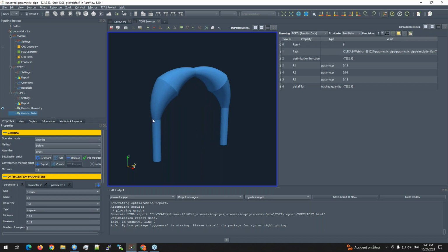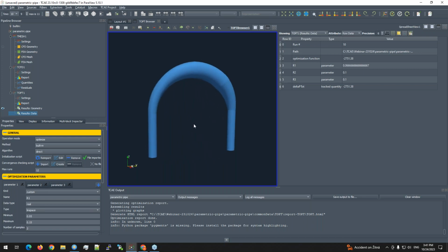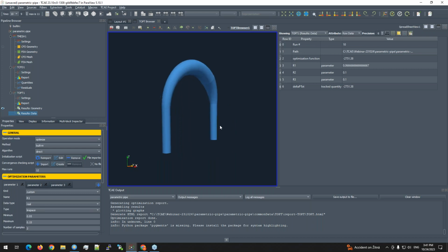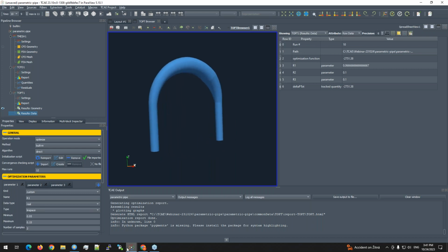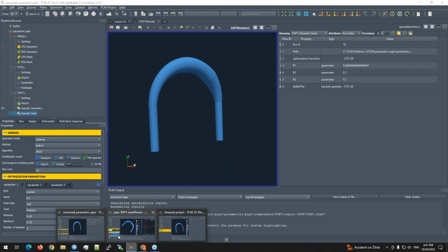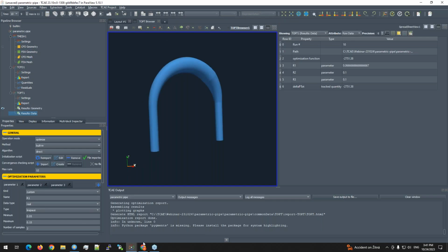And for example, in the next stage, what I would like to show you in this, let's say, artificial scenario, is to take the best efficiency point and now look for the real CFD parameters. I mean, real, that we would like to simulate with a finer mesh, which should be more accurate, and basically see the really final total pressure difference for this shape. So we can prepare a new case.